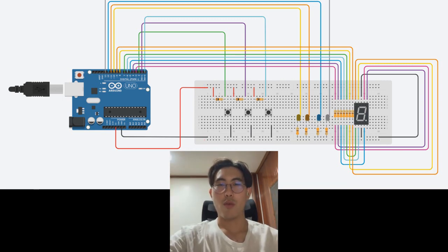The first step is placing the switches. Place our 3 switches on the breadboard. Each switch will be paired with a 10 kilo ohm resistor to ensure that we get a proper signal. The first switch will control the number of blinking LEDs.